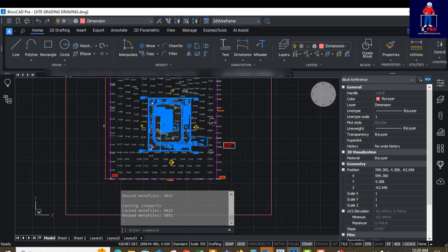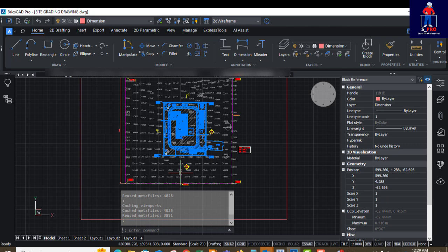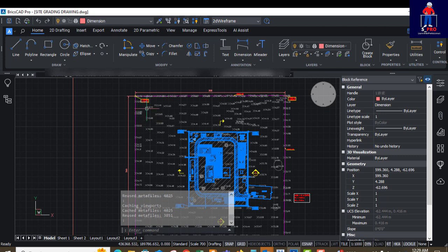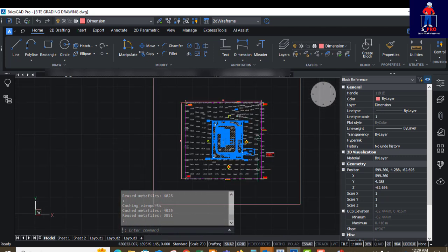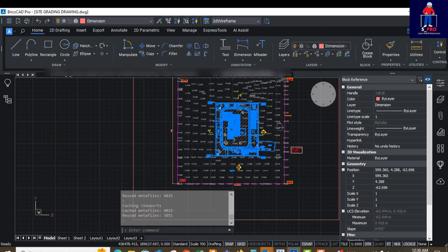So the first thing to do in site grading drawing is to go for a site visit. Yes, it is good to request a site visit, so that you can put a picture to what the topographical guys have done. Like I told us in the last class, this drawing here is a topographical drawing, so it has the spot height and the contours of the site.